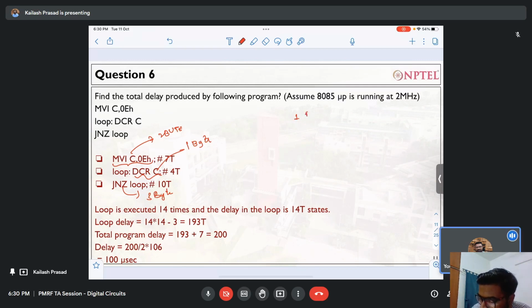Whenever you have a 1 byte instruction, it takes 4T states. Whenever you have a 2 byte instruction, it takes 7T states. And whenever you have a 3 byte instruction, it takes 10T states. Now, using that, we will try to answer this question.